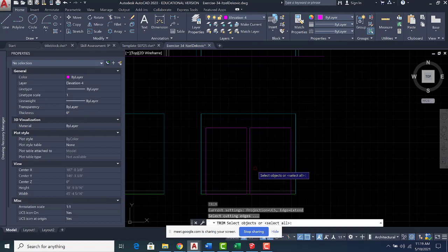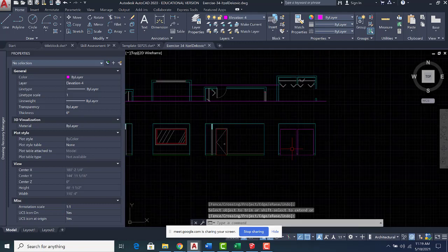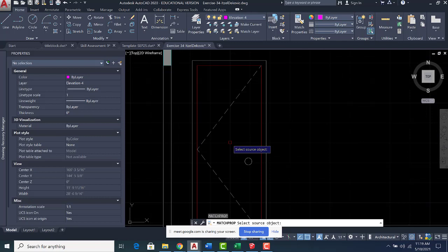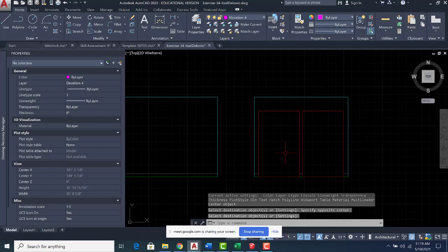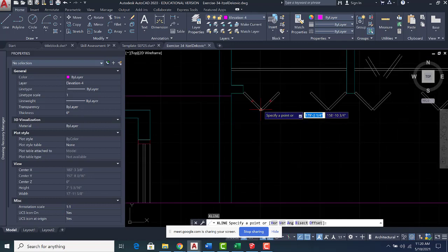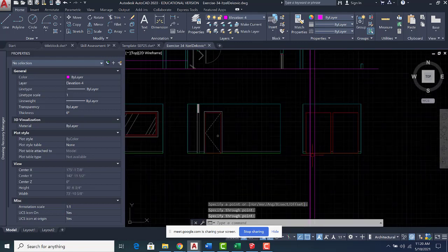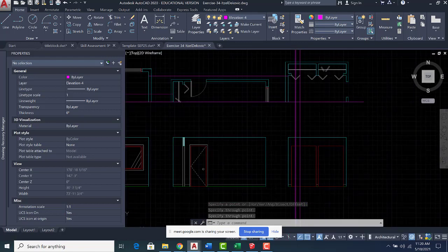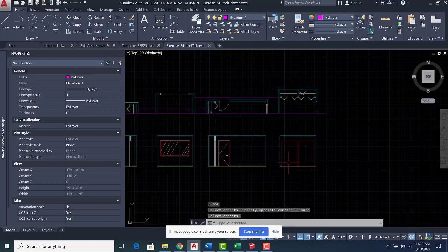So then I just trim. Remember, there is no baseboard when we have the opening. Then I just match it with this door opening here. Now I have to add my door. Please do not do it this way. It's the wrong thing to do. I have a student that, even in residential, they don't learn it correct and then they do it this way. This is wrong. We don't show the door open. We always show the door closed in elevation, and it's really simple.